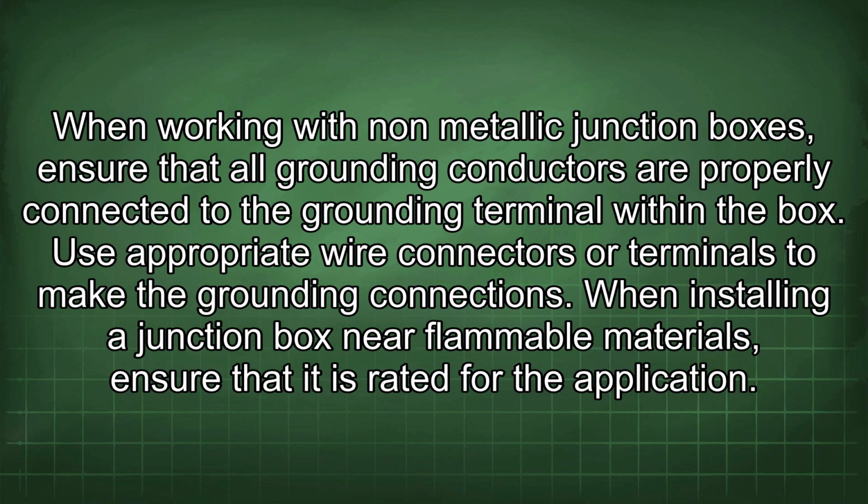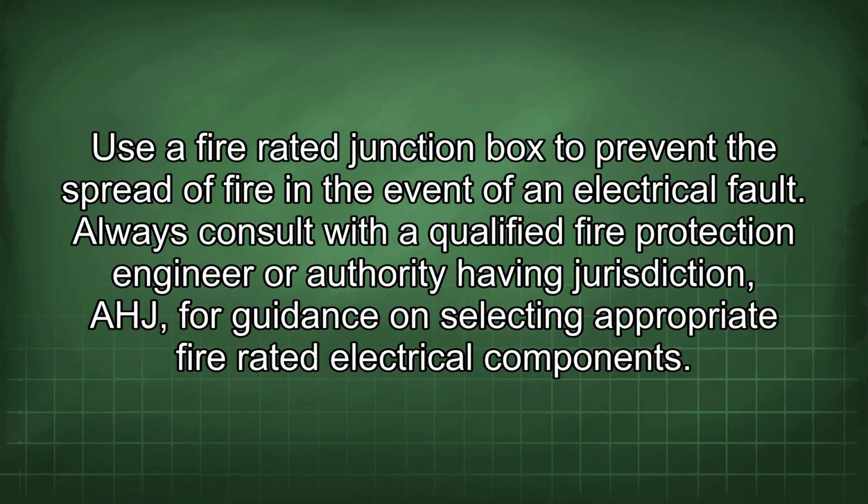When installing a junction box near flammable materials, ensure that it is rated for the application. Use a fire-rated junction box to prevent the spread of fire in the event of an electrical fault. Always consult with a qualified fire protection engineer or authority having jurisdiction for guidance on selecting appropriate fire-rated electrical components.